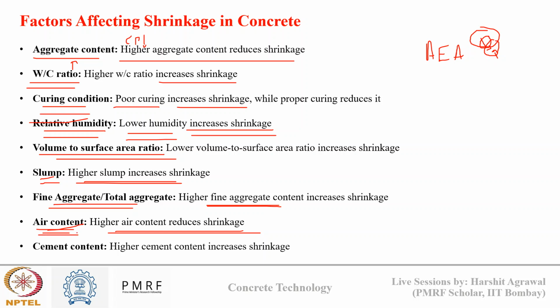If I have air voids inside concrete, the tensile stress that is generated due to shrinkage gets relieved due to the air void. Okay, however, if there is excess air content in concrete, it will reduce the strength of concrete also, which can increase the shrinkage. So air content, though it reduces shrinkage, if there is very high air content, it can increase the shrinkage also.